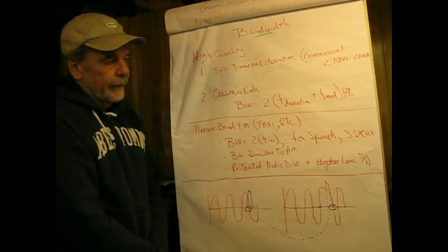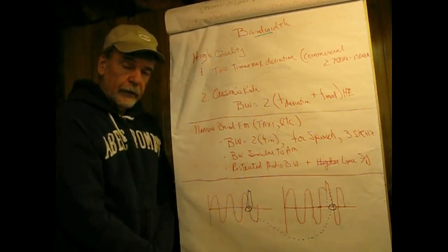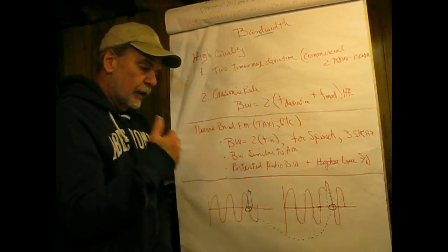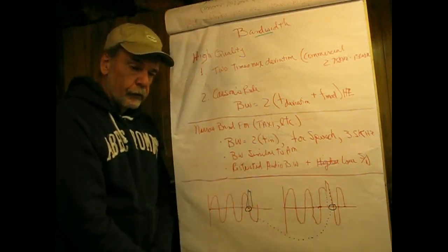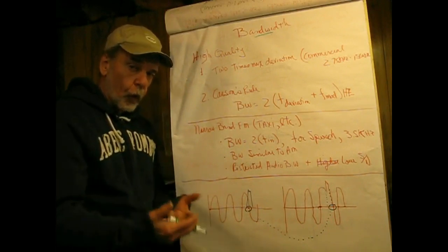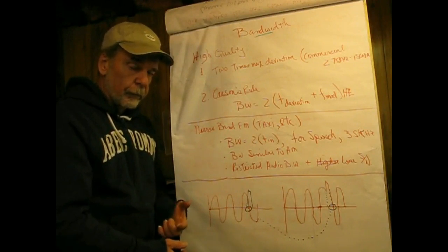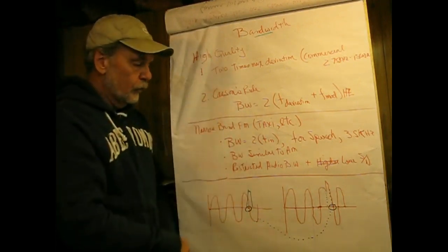Now, what the actual bandwidth is, it can go out to infinity. But as the outermost sidebands become lower in amplitude, they contribute less and less to the overall quality of the signal, especially the signal-to-noise ratio. So when we say bandwidth, these are practical bandwidths.